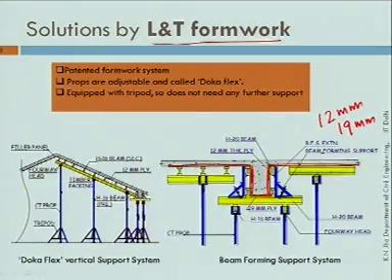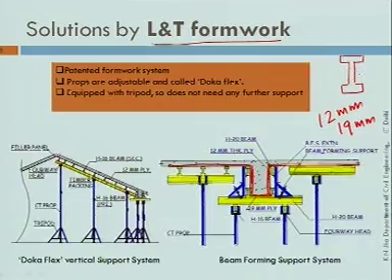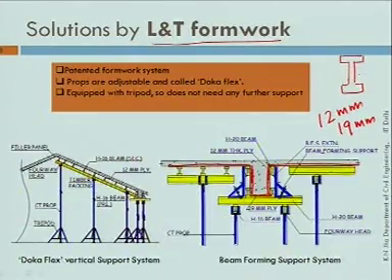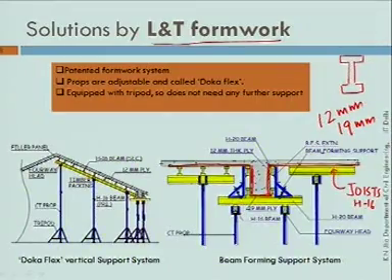Then underneath this plywood they use this H16 beam, which is having a cross section like this. As I told you, these beams are made up of timber and plywood. So the yellow one, what you see here, you can refer to them as joists. So joist here is made up of H16 beams. Now stringers also, you can notice this beam here.